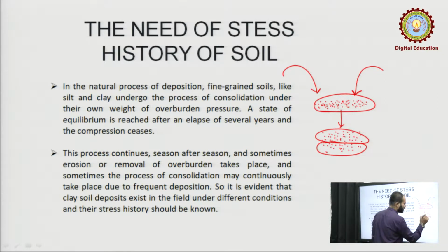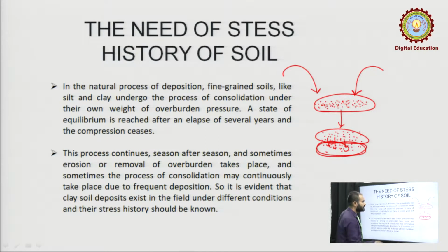This part will exert stress on the lower part, due to which it will get compacted or consolidated to an extent. So, under its own overburden pressure, consolidation can take place, mainly in fine grained soil.